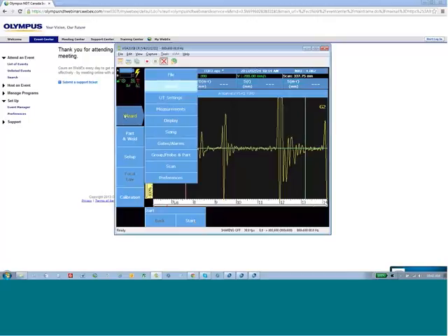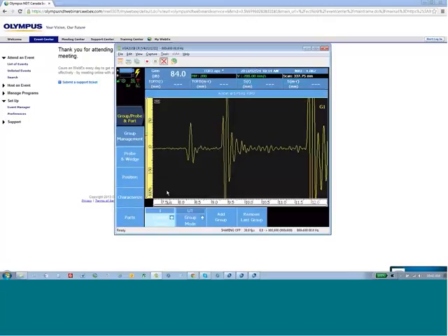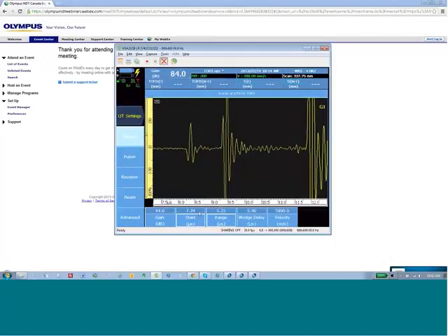So we have our UT group, our TOFD group now set up and visible. We want to set our range on the UT setup so that we can see approximately a microsecond in front of the lateral wave, and maybe the mode converted shear wave and some distance in back of that, depending on the procedure and the preference.